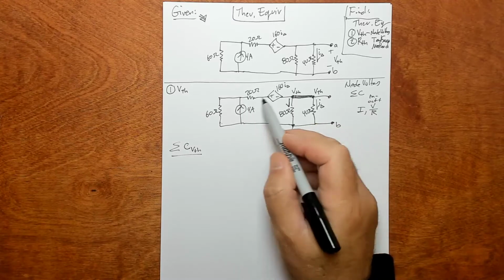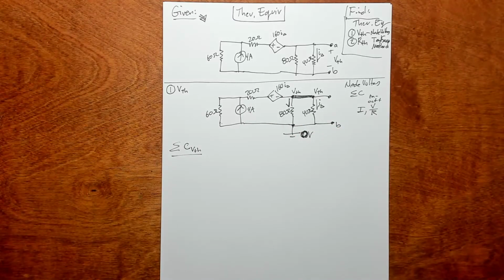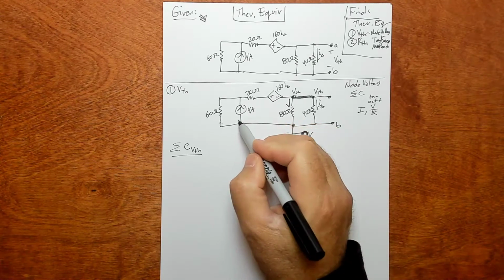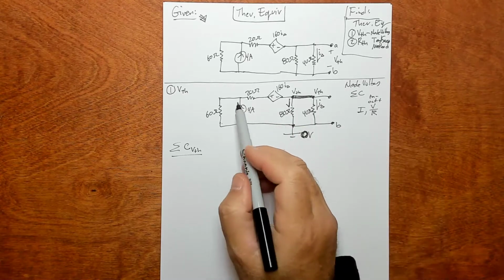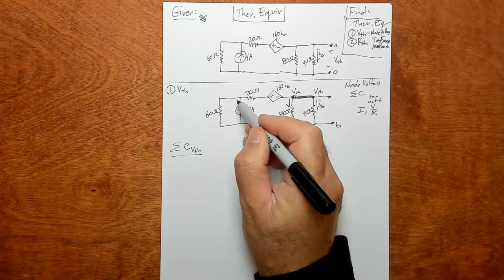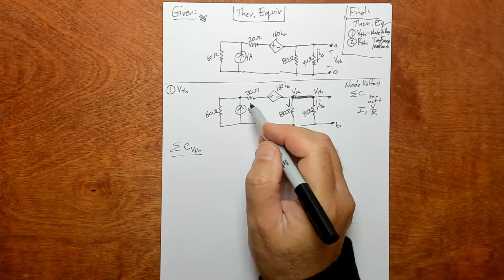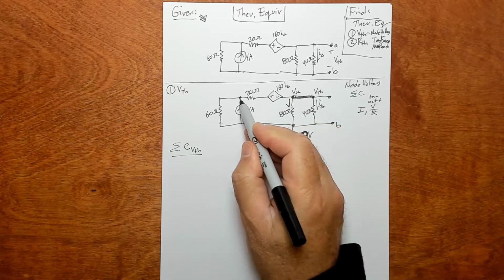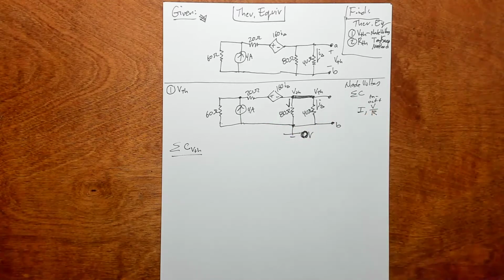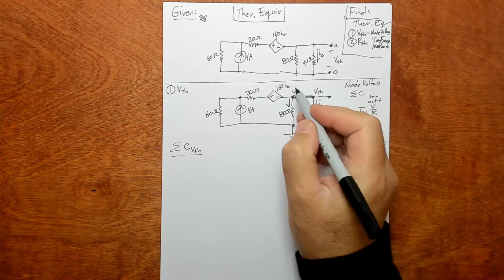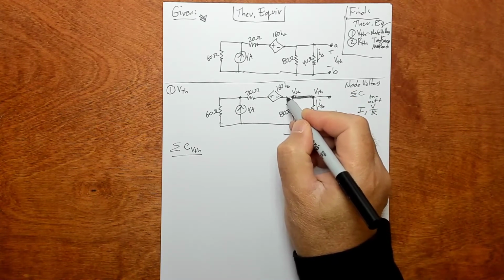Yeah, the current in this branch is very much a guess. Let's look over here and try to guess this a little better. There's no real good way to guess which way the currents are going in here. This guy here, I'm going to need another node voltage equation, which isn't obvious at this point, but I'm going to need that. So I'm guessing on these currents here.